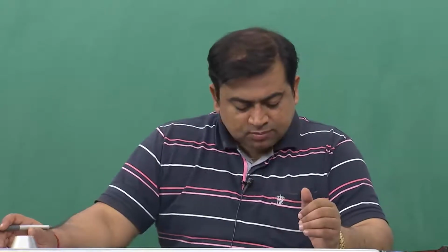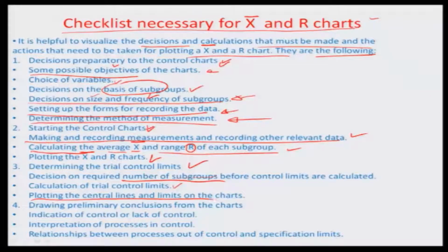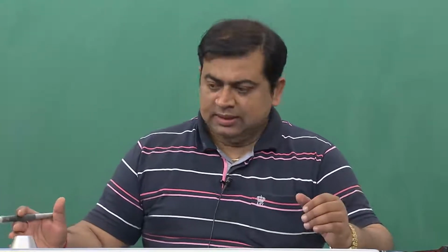Okay. And then you plot the center lines and the limits, and the idea is that all observations that you are recording would keep on continuing to be between these two limits and the central line, and then you can give an estimation of whether the process is going towards one side of the mean, to the other side of the mean, or away from the control limits. So all these things can be judged. If you have continuous monitoring of the quality, this is the best basis, that whenever something goes outside the UCL, the upper control limit, or the lower control limit, you can say that the process is going out of control and take a countermeasure so that it can come back to normal levels.